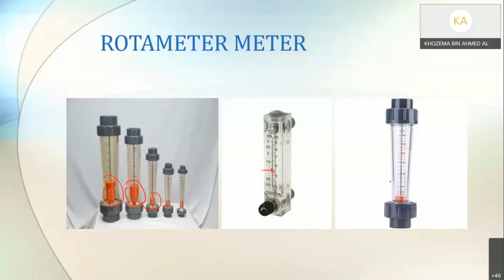Then this one is again a different type of rotameter. This is actually a 3D view of a rotameter. Flow will come from here, and then the float will go up until it reaches equilibrium. There will be a value here where you can read it. You can see that the diameter initially and the diameter at the top are a little bit different because of the taper. So you will have a taper coefficient to decide how much is the angle of change. That is how a rotameter works.